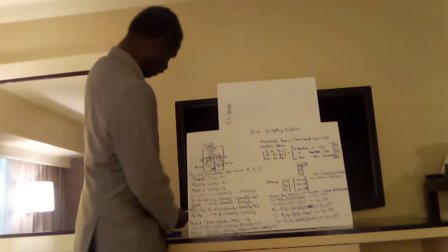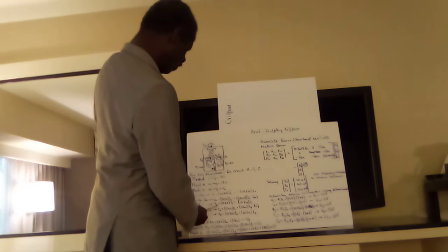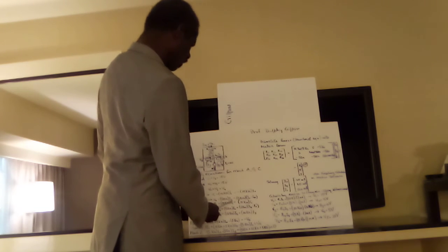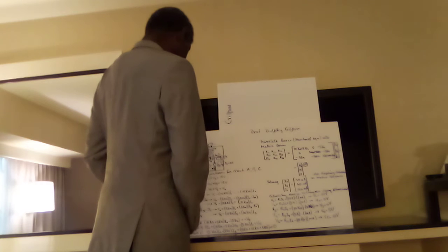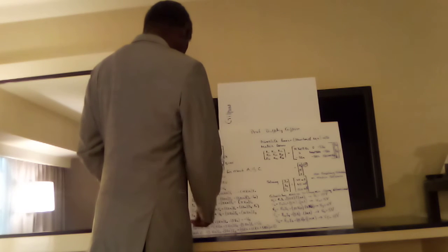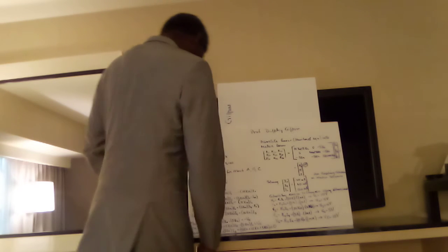I3 is now equal to IC, and this gives rise to V3 equal to 10 kilo ohms times I3. That is using V equals IR. We're using KVL, Kirchhoff voltage law, and Kirchhoff current law in combination with Ohm's law, and that's equal to 10 kilo ohms times IC.